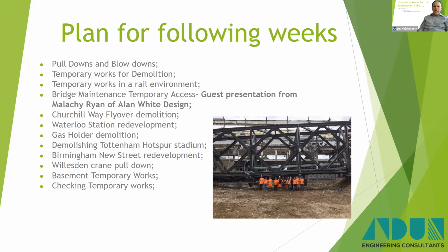They've got a system they used on the Broadmarsh Centre, a car park in Nottingham near the Broadmarsh Centre, where they have a large scale cantilevering steel frame that sits on the ground with counterweight at the base and has timber protection down the face. And they then move that along the structure, and that will prevent any rubble leaving the site. Well, that's the proposal anyway. I've not been involved with the design or anything, but I've seen it at an Institution of Demolition Engineers presentation. So if you have a look on AR Demolition's website, you'll see one possible solution.